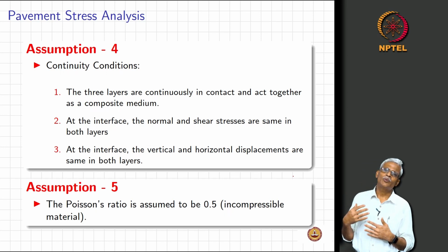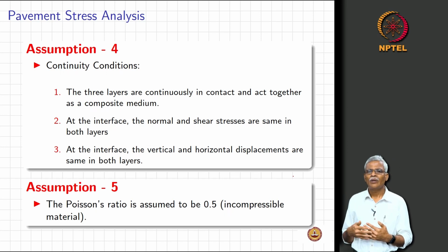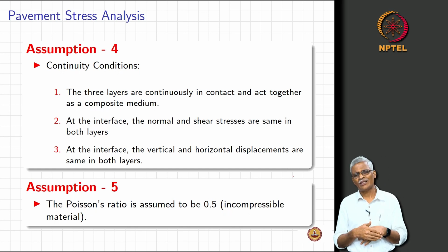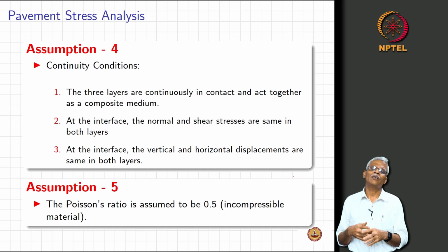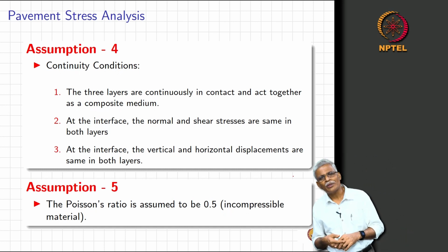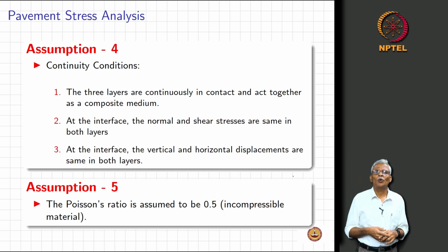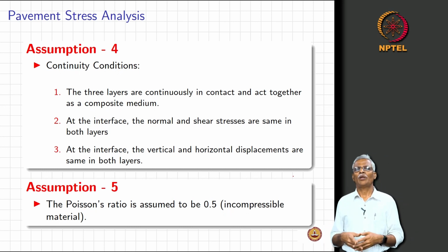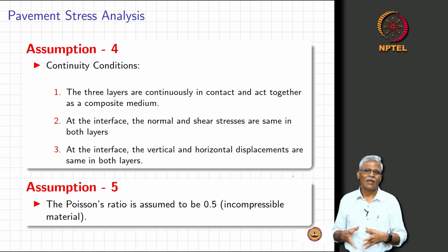Now, do this prime coat and tack coat induce some kind of adhesive nature? Not necessarily so, and in fact the opinion is divided. There were many instances in which pavement engineers in the US and Europe constructed pavements without a tack coat or without a prime coat and nothing happened.